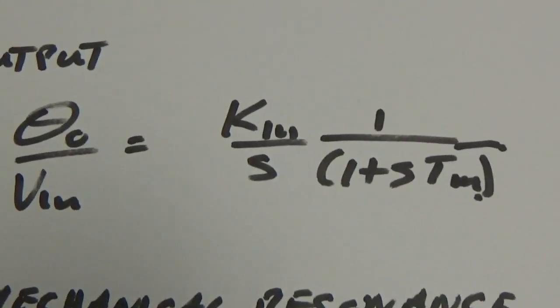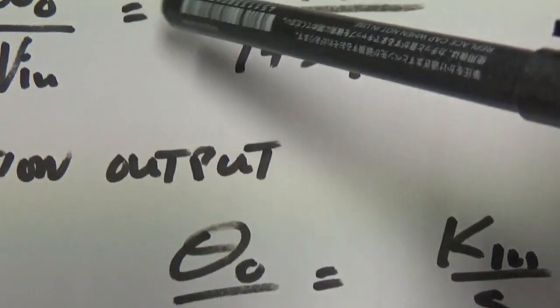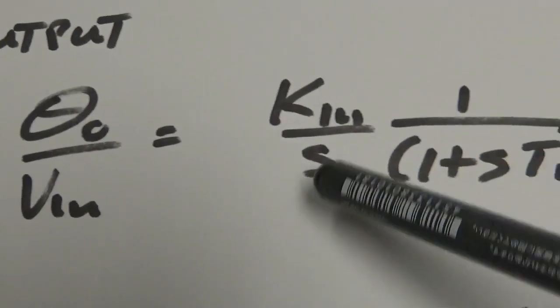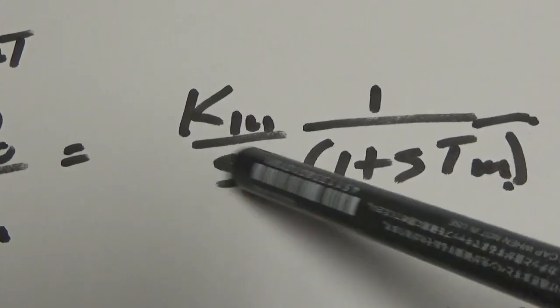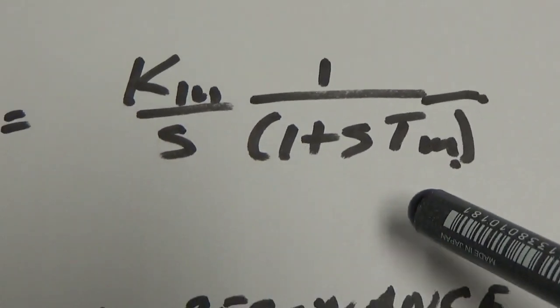The actual transfer function we've got, however, is an integrated form of that, because we want position and not velocity. Velocity is just a first order transfer function. Position's got an extra k over s term. So that becomes a second order transfer function that we're trying to identify.